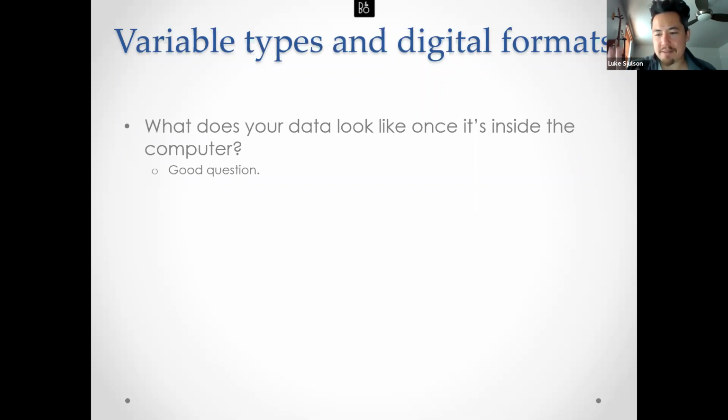Mice make these calls at, I forget exactly the frequencies, but it might be like 50 kilohertz or something like that. So we have to have our low pass filter set higher than the highest frequency sounds that a mouse is capable of making. And then we need to sample at a multiple of 3 of that. Our electrophysiology setup samples at 20 or 30 kilohertz, but mice are making these things at like 50 kilohertz. So we had to buy this special microphone that samples at something like 220 kilohertz, and has low pass filters somewhere around 90 or 80 kilohertz or something like that. And then we'll have to sample those things separately and then synchronize them post hoc.